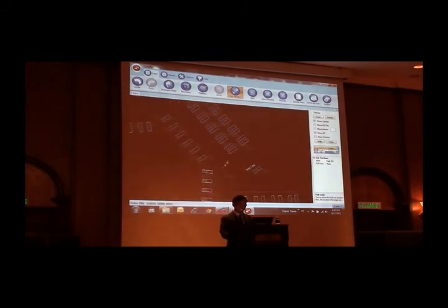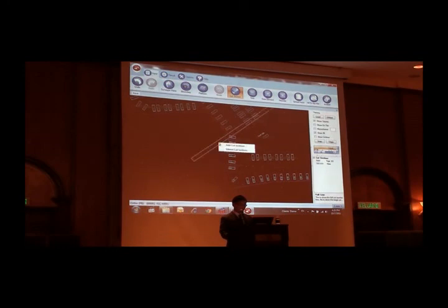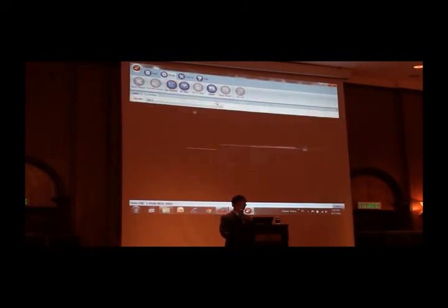And then I will extend again the cut section. Same, I add more cut section up to here. Interval 10 meters. So immediately we get all the cut sections done. Okay, you can see all the cut sections. It's done. Cut 1, cut 2, cut 3.